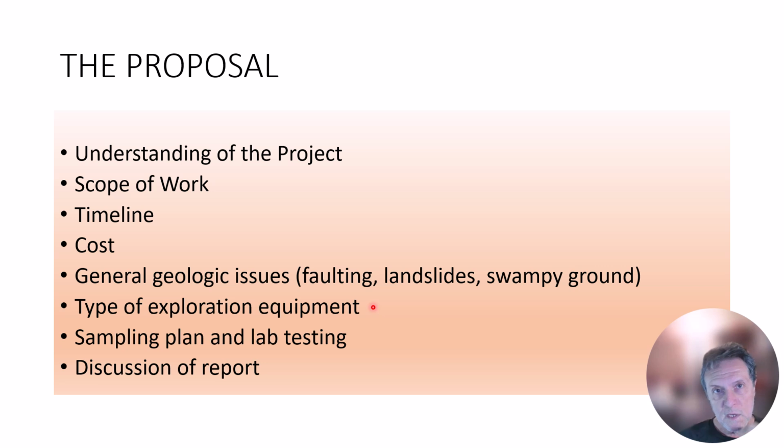It should include the type of exploration equipment you're going to use. Should have a plan for sampling, the depths at which samples are obtained and the types of samples which will be obtained, a preliminary lab testing program, and then a discussion of the report and what it's going to contain.